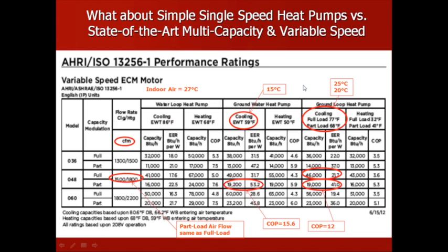Personally, I am very disappointed in this because they let people rate in the cooling mode at temperatures of 59 degrees on the condenser, and the indoor air is at 27. And you get an EER of 53, which the marketing people like to throw out there, and so folks think that they're going to get a 53 EER and it's going to be so great and wonderful, but in fact they don't recognize they will never have these conditions.